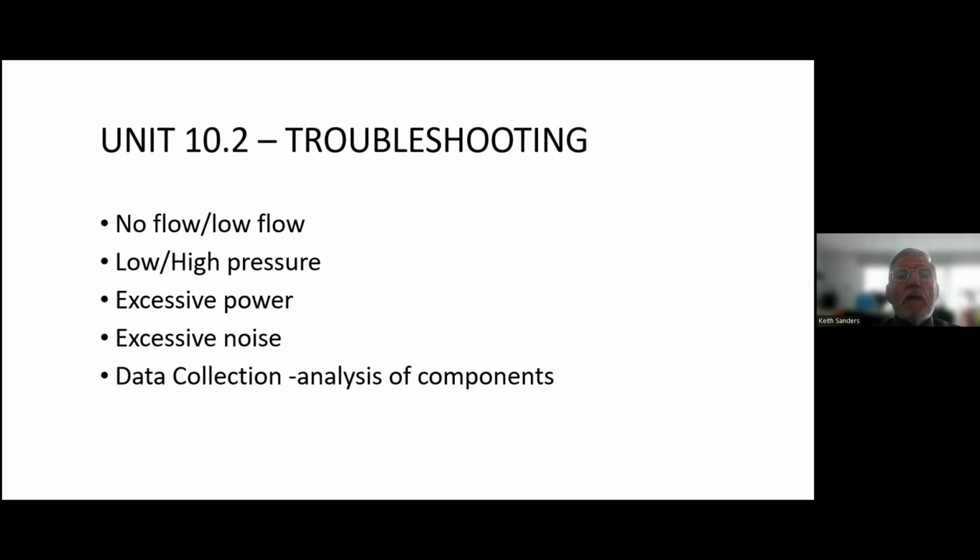And then finally, we're going to look at troubleshooting, typical common faults when the pump's not delivering the quantity that people are expecting, it's not delivering the pressure that people are expecting, it's consuming excessive power, and it's making excessive noise.